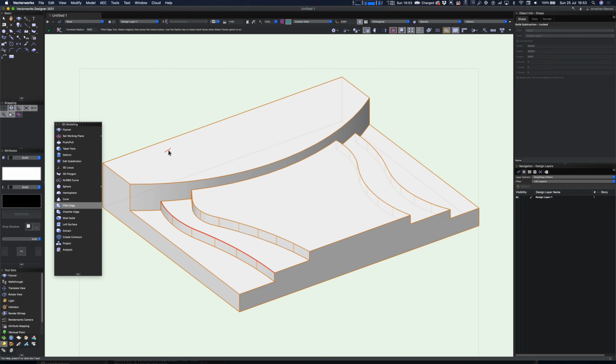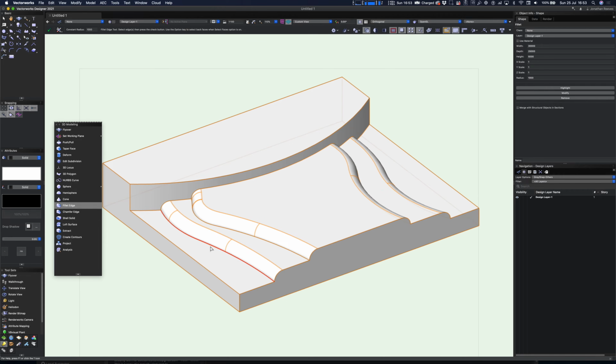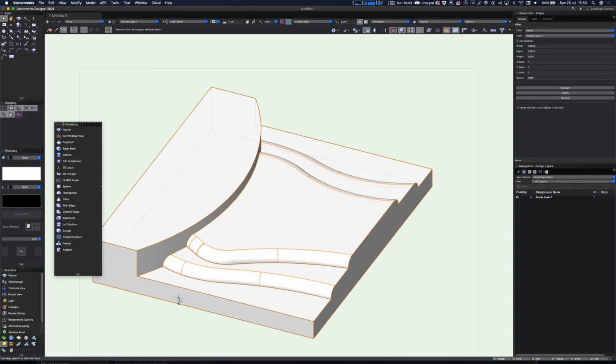So I'm going to go onto the 3D fillet edging tool, and I'm basically going to set a radius up at the top there, and just basically click and highlight. Now you can easily modify those if you want to, and the good thing about modification is you can reselect the highlight, can you see, and hold shift down, select other edges, and then click tick. So all 4 of those basic fillets were in the same command. Let's see if we can do the same thing on these ones. It might be better to do those individually, to be honest. So let's have a little look.